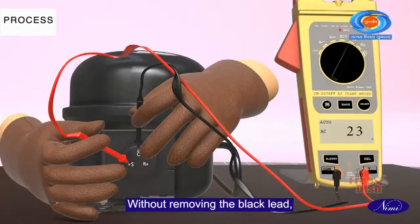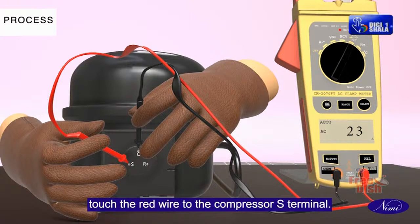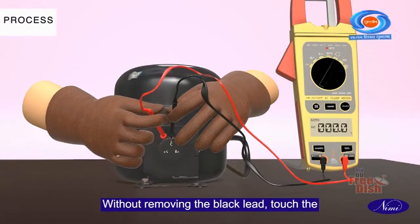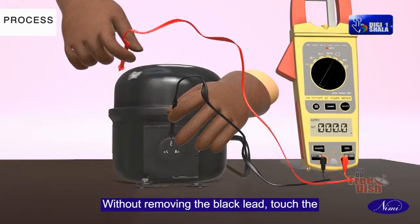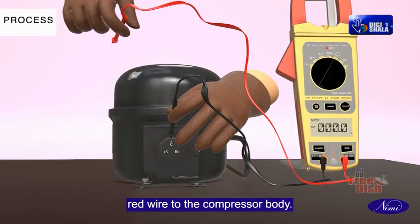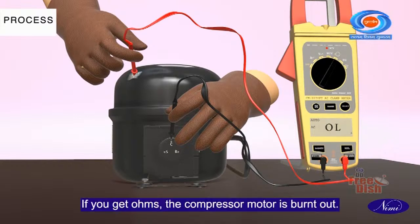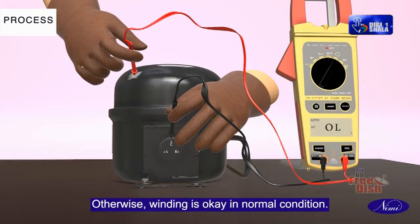Without removing the black lead, touch the red wire to the compressor S terminal. This will give the starting winding ohms. Without removing the black lead, touch the red wire to the compressor body. If you get ohms, the compressor motor is burnt out. Otherwise, the winding is okay and in normal condition.